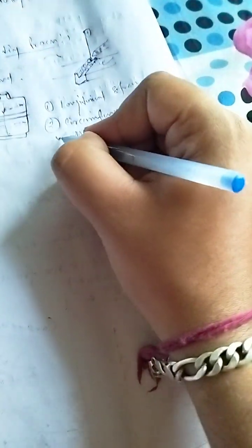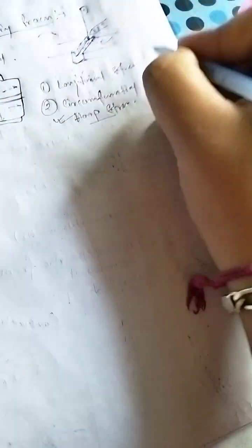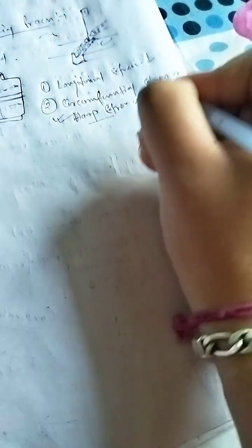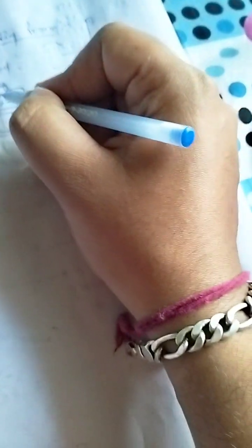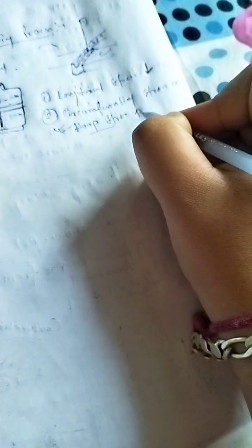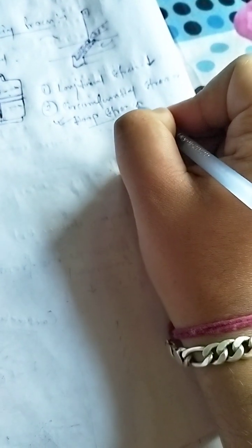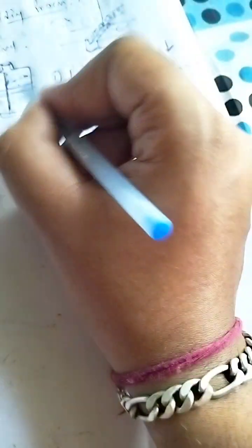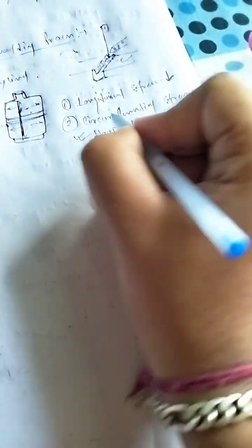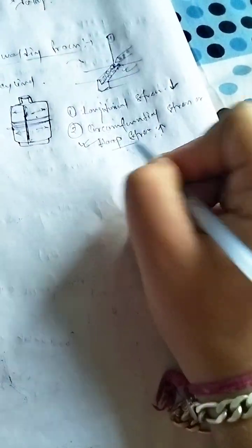Inside the gas cylinder the hoop stress is greater, and the longitudinal stress is less. If welding is performed vertically, it offers more longitudinal stress and less of the circumferential or hoop stress. But the hoop stress is the primary stress. For that reason we go for circumferential welding, so that it resists the hoop stress. This is the main reason.